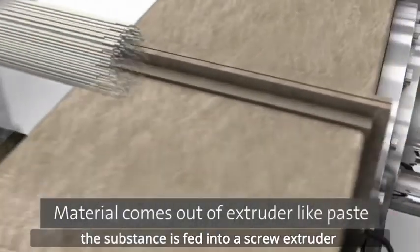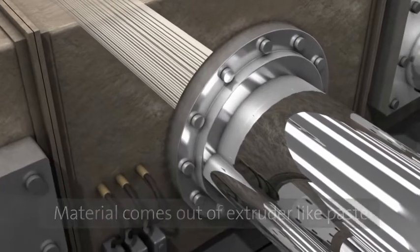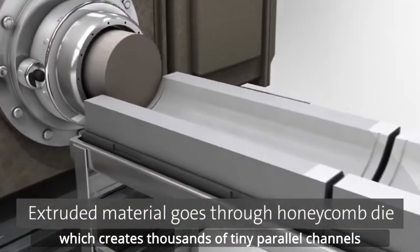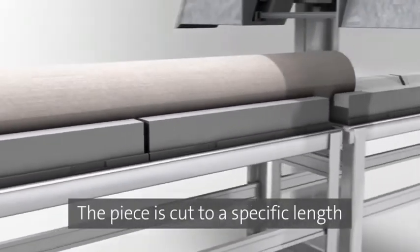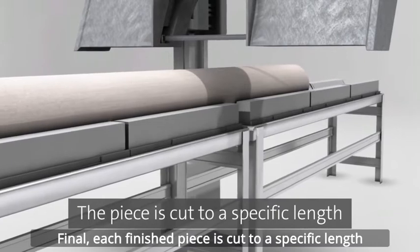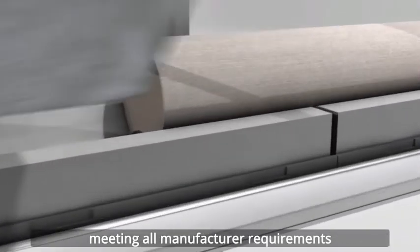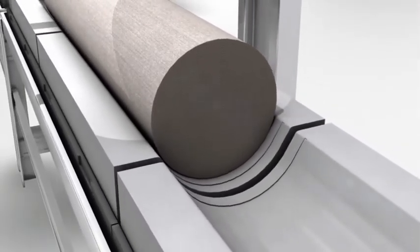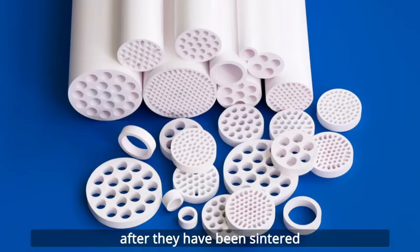The substance is fed into a screw extruder and through a honeycomb die, which creates thousands of tiny parallel channels. Finally, each finished piece is cut to a special length, meeting all manufacturer's requirements. We are showing some extrusion-formed ceramic parts after they have been well sintered.